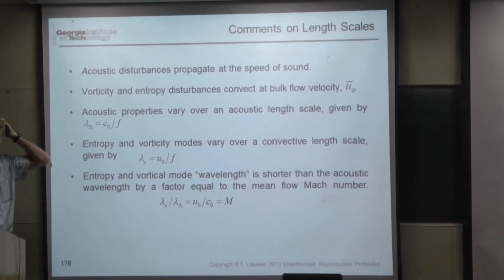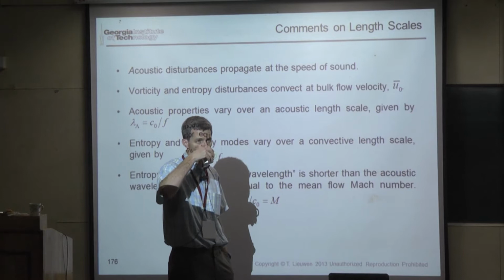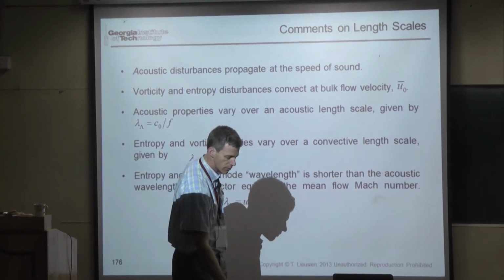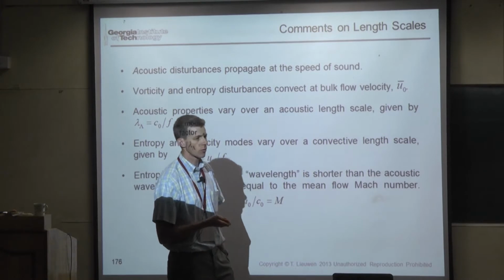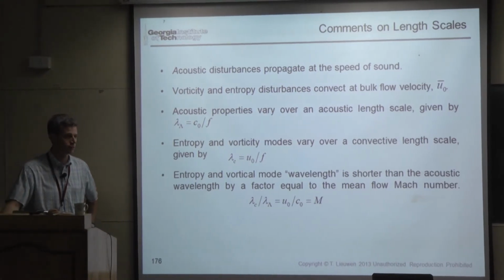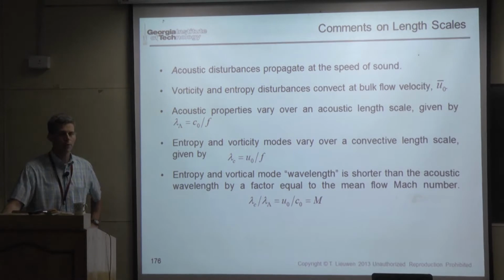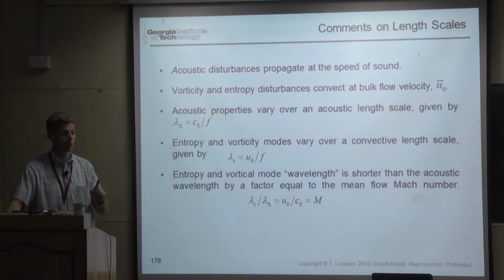Question? Yes? The vortical disturbance is not influencing temperature because it is inviscid, considering the viscous distribution? It's also because it's incompressible at this order. At first order, the vortical disturbance causes no change in density or pressure, or therefore temperature. If I included viscosity, if I linearized it and added a viscous term, would the vorticity induce a temperature fluctuation? I think the answer is still no. I have to think about that one, but I'm pretty certain the answer would still be no within the linear approximation.